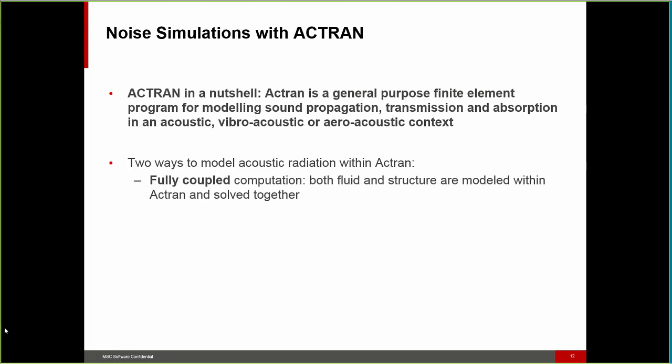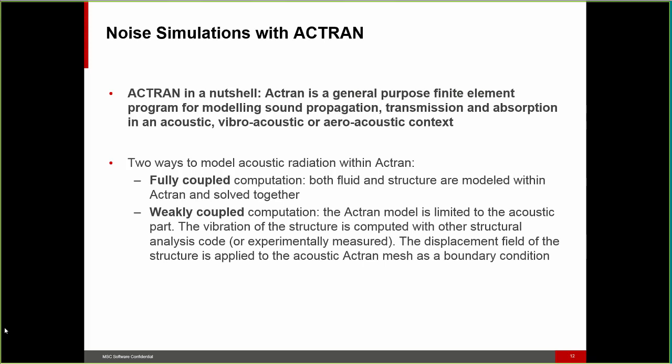A fully coupled computation is where both the fluid and the structure are modeled within Actran and they're solved together. A weakly coupled computation, on the other hand, is where the Actran model is limited to the acoustic part only. The vibration of the structure is computed with other structural analysis code, or it can be experimentally measured. The displacement field of the structure is applied to the acoustic mesh by a boundary condition in Actran.